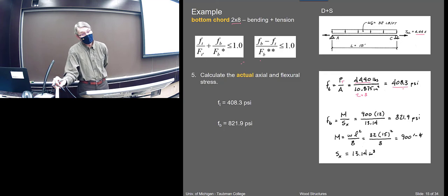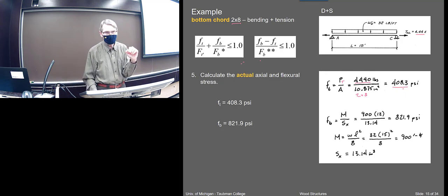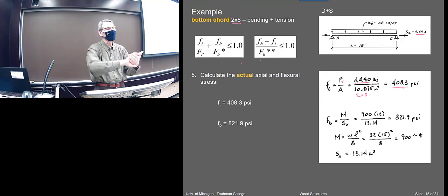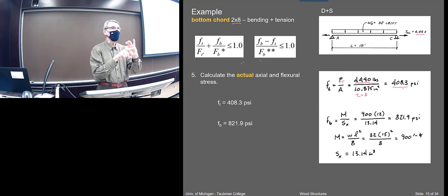The other thing, the aside here, that I'm kind of ignoring, is that it depends how that truss is built. Most trusses have a gusset plate. Gang-Nail makes these lovely metal plates that just press on, and that doesn't reduce the area at all, right? They just press in there. On bigger trusses you could maybe cut a hole and bolt them together.